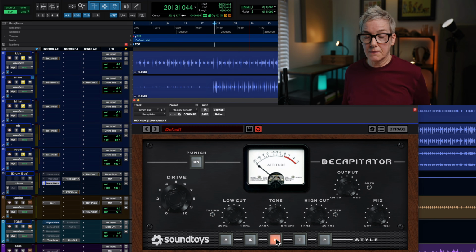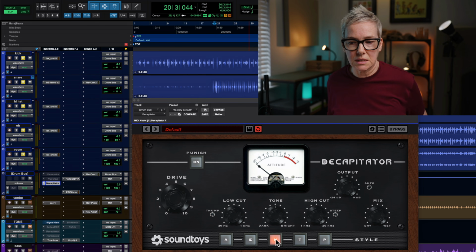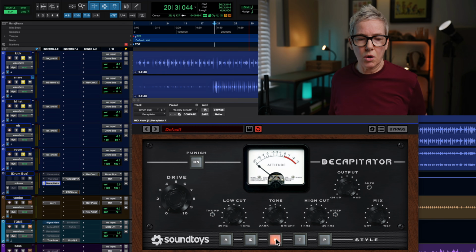N is a Neve console input. Neve we associate with being warmer sounding. However, the sound of this is based around the transistors involved in that circuit. I think it's the 1057 Neve input section. So this Neve is all about transistors, and the distortion from transistors can be perceived as being more aggressive than tube. They produce generally more odd order harmonics.